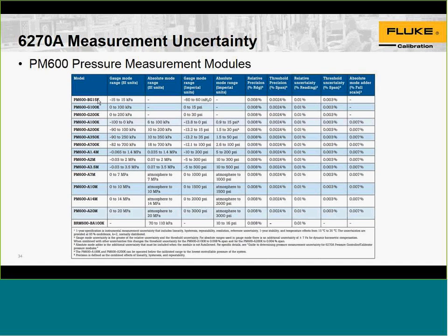A verifying question came up on the 7615 and using a different fluid. It asks if we use HT200 on the 7615, does it have to be calibrated for that fluid? We don't. There's like 25 fluids that I've seen in our fluid pools, but our references use Monoplex DOS, which is a mineral oil.